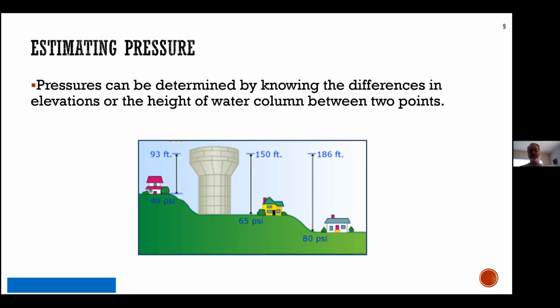And if I go further down the hill, this guy's got 80 psi, so he can knock his neighbor's cat off the fence if he wants. The water level in the tank hasn't changed, but he now has 80 psi, so double. And all of that is a result of change in elevation. So as an operator in a system, you may have areas where the pressure is really good and your customers are happy, or up an elevated area, the pressure starts to diminish.